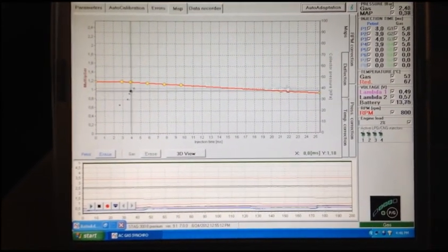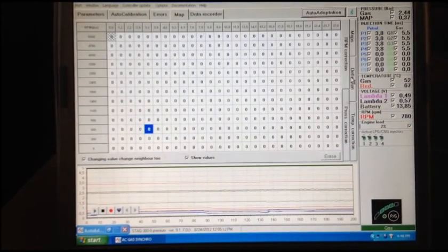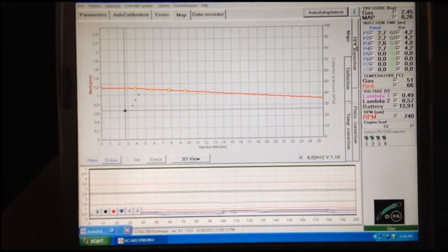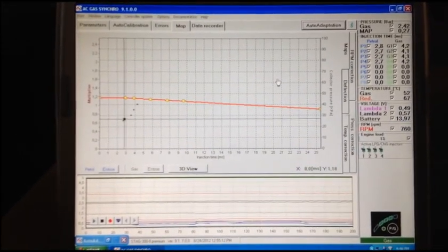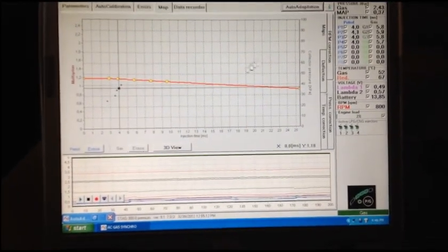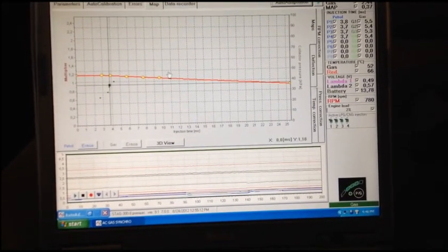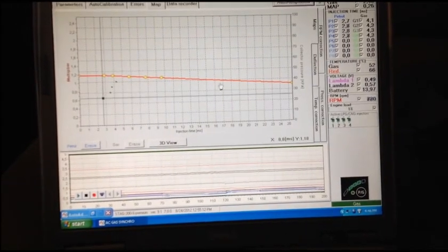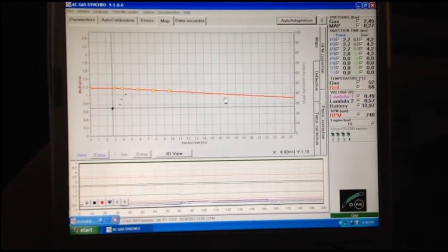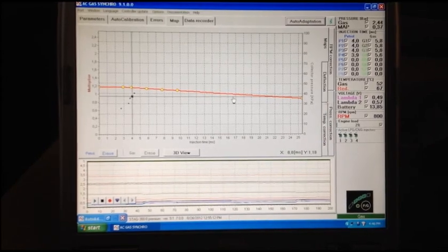This grid right here, there are many other ways you can make corrections under more difficult to tune cars. You can go into different types of graphs and get really specific. For the most part, I'd say 95% of cars you can get it dialed in with just this screen. You can add in multiple dots here. You can right click anywhere in here and add in more correction points and manipulate these up and down to get your correction suitable. So let's go for a similar drive in similar conditions on natural gas, and let it build its chart for that.